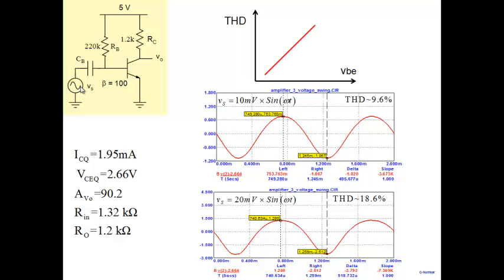I don't know if a natural solution is coming. If I have an input which is 20 millivolt, why don't I attenuate it, make it 10 millivolts, and then apply it? Does it seem logical? I want to amplify a signal, so what do I do first? I have a 20 millivolt signal, first I attenuate it. I make the signal weak. From 20 to 10 I make it, and then I feed in 10 here. So I can use a voltage divider and make it 10, and then I'll get 10% distortion. Does it make sense that you should attenuate a signal and then amplify it?